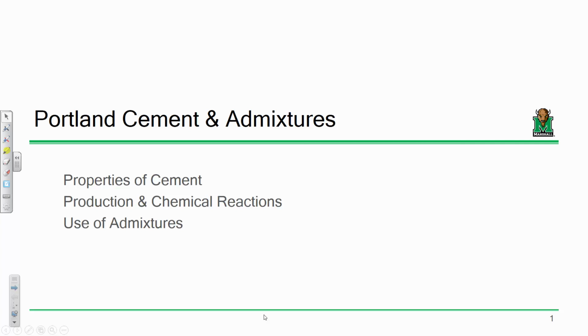I mean, we are civil engineers. Concrete is a material that we will use throughout our careers. So being able to proportion a concrete mix is very important. All the stuff that we did with aggregates, a lot of our focus was on determining some very key properties: specific gravities, absorptions, fineness modulus, moisture contents. All of those values are going to ultimately be used to proportion and design a concrete mix.